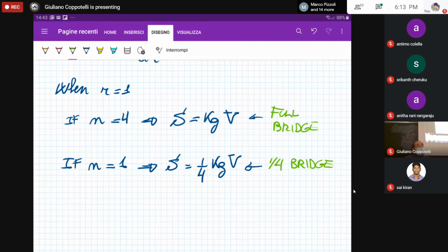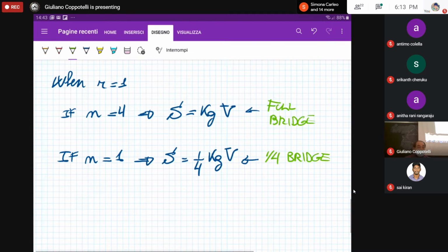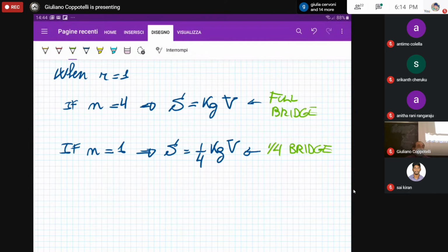By using this measuring circuit, the sensitivity depends on the strain gauge factor, whose order of magnitude is unity, equal to 2, times the input tension, that is some volts. So just by using some volts and the typical strain gauge factor, you have a Wheatstone bridge giving you a sensitivity of some volts per microstrain, and therefore you are very happy about it, because it gives you the right sensitivity.